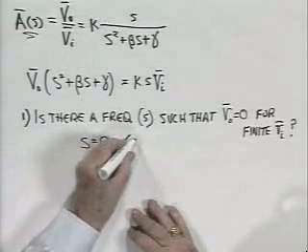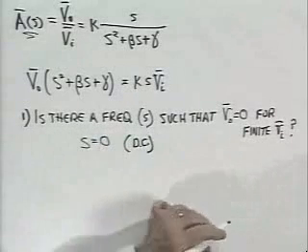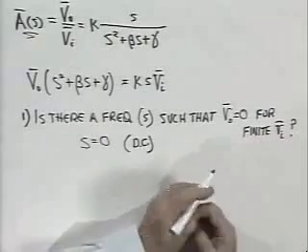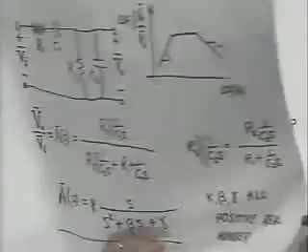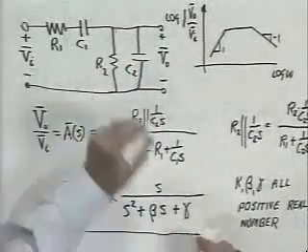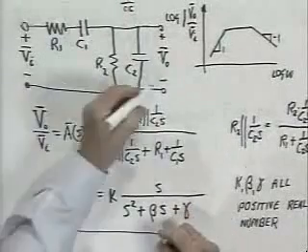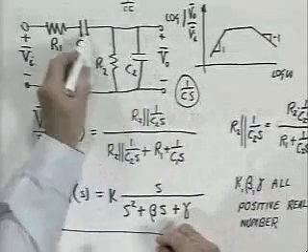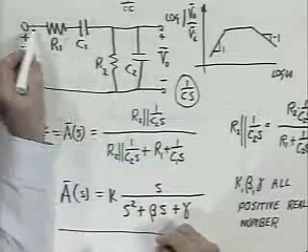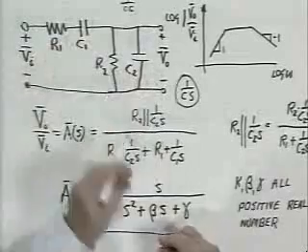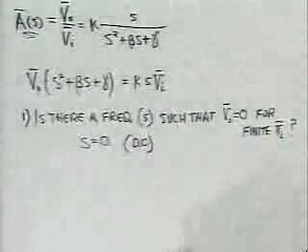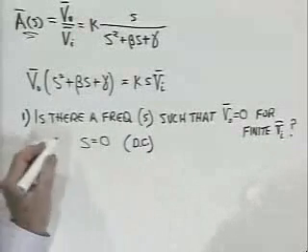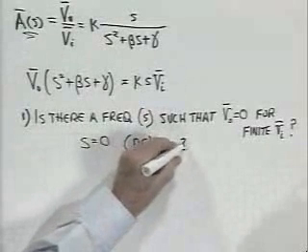Well, pretty clear that there is, and it is s equals 0. That is, this frequency is s equals 0, which means, of course, nothing is changing with time, or we have a DC condition. It may seem trivial, but at that real frequency, s equals 0, there is no output from this circuit because both these capacitors, which have impedances which vary like 1 over Cs, look more and more like open circuits as I go lower and lower in frequency toward 0. And if this capacitor is an open circuit, there is no way for a signal here to get through to here. This is an open. So that checks what ought to be the case intuitively. Such frequencies in a transfer ratio are called zeros.